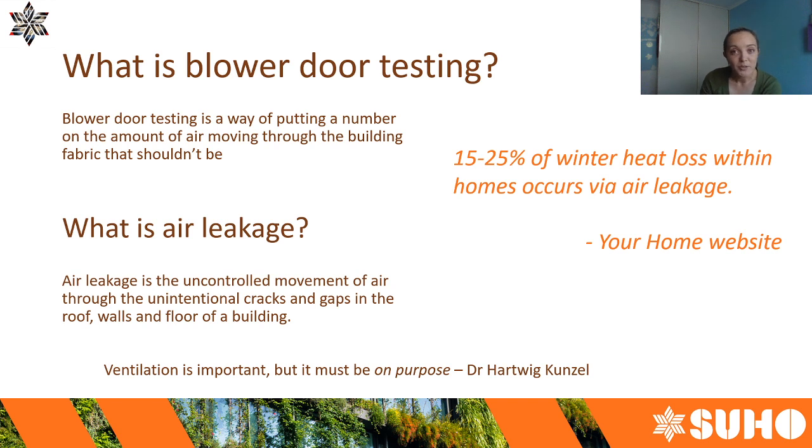So what is blower door testing? Blower door testing is basically a way of quantifying the air leakage within a building. Air leakage is defined as the uncontrolled movement of air through the unintentional cracks and gaps in the roof, walls, and floor of a building. It's important not to get that confused with ventilation. Ventilation can either be passive using your doors and your windows, or it can be mechanical using a mechanical ventilation system. That is not what we're talking about when we talk about air leakage.